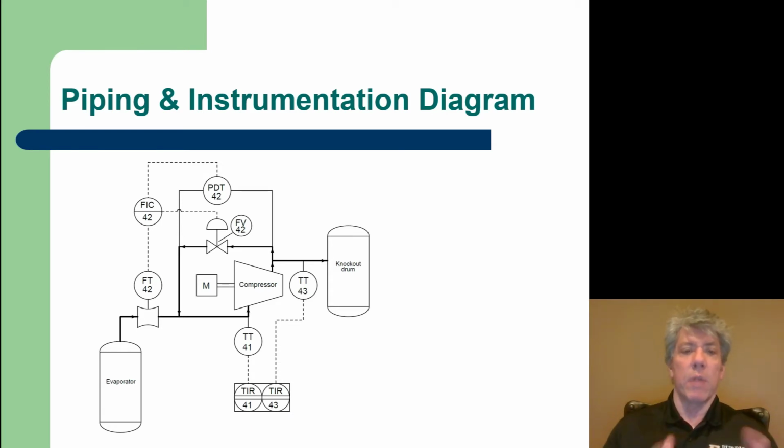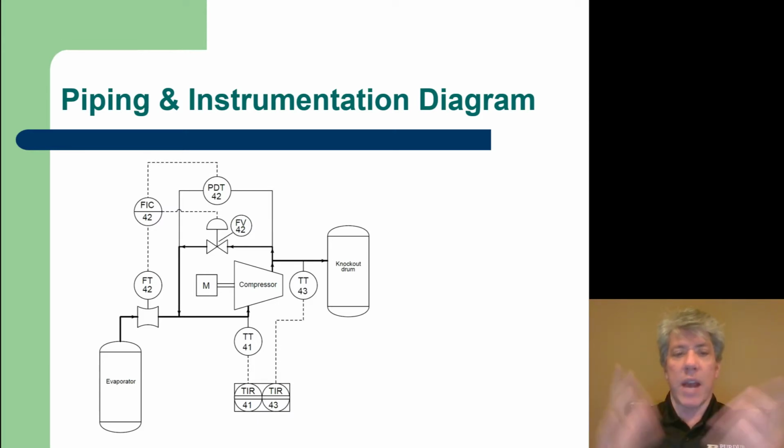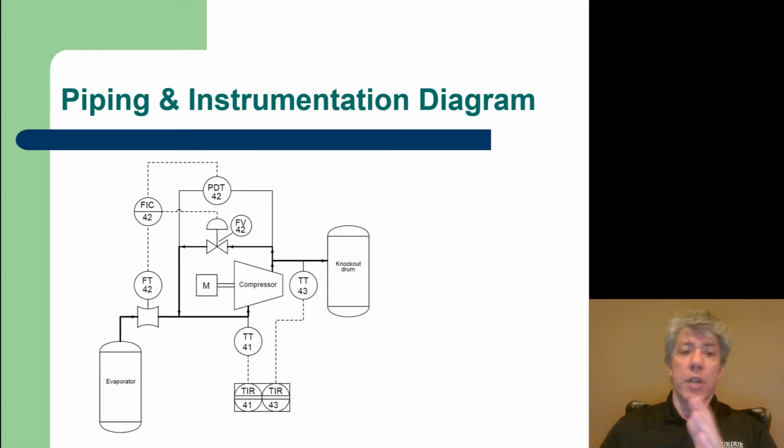We can still see the flow of the fluid going from the evaporator, but then it goes into this sort of an hourglass shaped item. And what is that? Well, that's most likely a venturi tube. Venturis can be used to change the pressure of the flowing stream, because they neck down, so the velocity increases and the pressure decreases because of conservation of energy. And so if we measure the pressure in the throat of the venturi, the smallest area, given knowledge about the venturi, we can determine the flow rate. Or really it's a pressure drop that's measured, but that gets transformed into a flow rate.